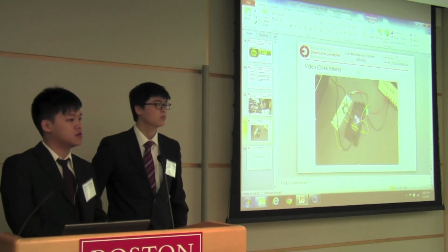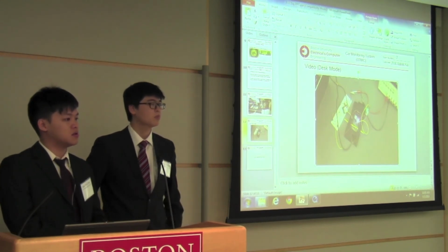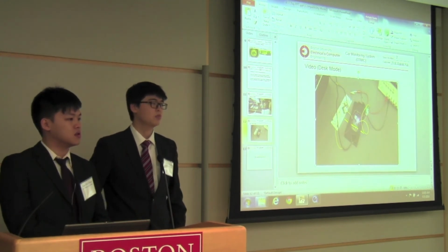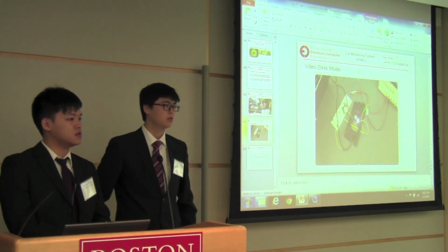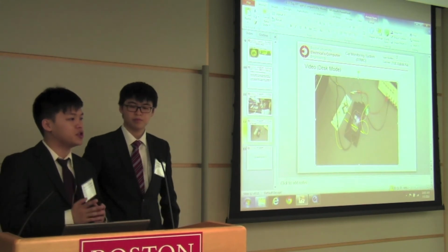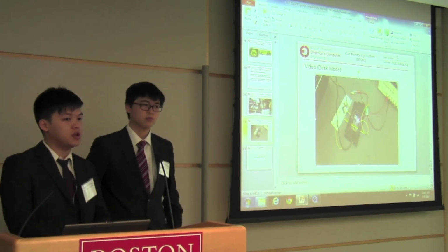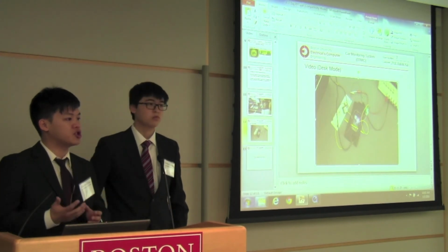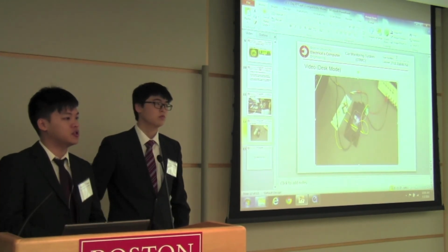You have a microcontroller as well as a Raspberry Pi. Yes. The micro detects the event, sends it to the Pi which takes the picture, and then it sends it back to the micro. Right. Why do you have a micro and a Raspberry Pi? Because everything going external to the user's phone will go through the GPRS module on the microcontroller, and the Raspberry Pi is just where we store the video and the picture.